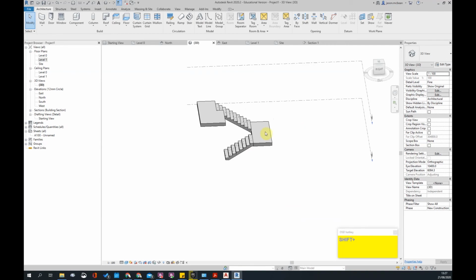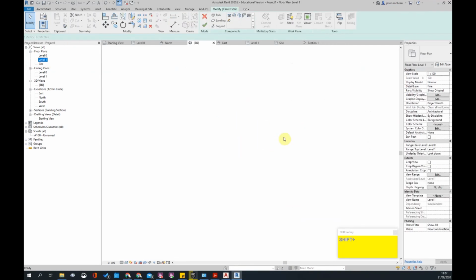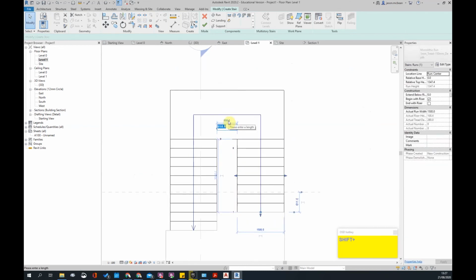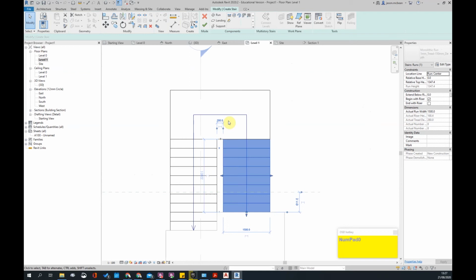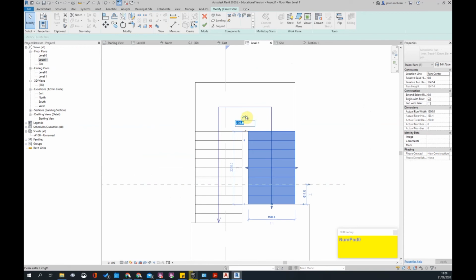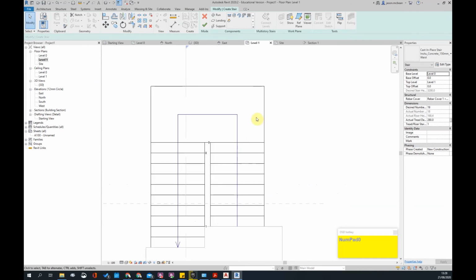Okay. So generally, what I'm referring to there, if I go to edit stair, generally I'll try and make this 200, just so that there's enough space when you put the railing on so that your hand can, maybe generally 160 is what I also work with from time to time. So you've got enough space for the railing to go around the stair in essence.